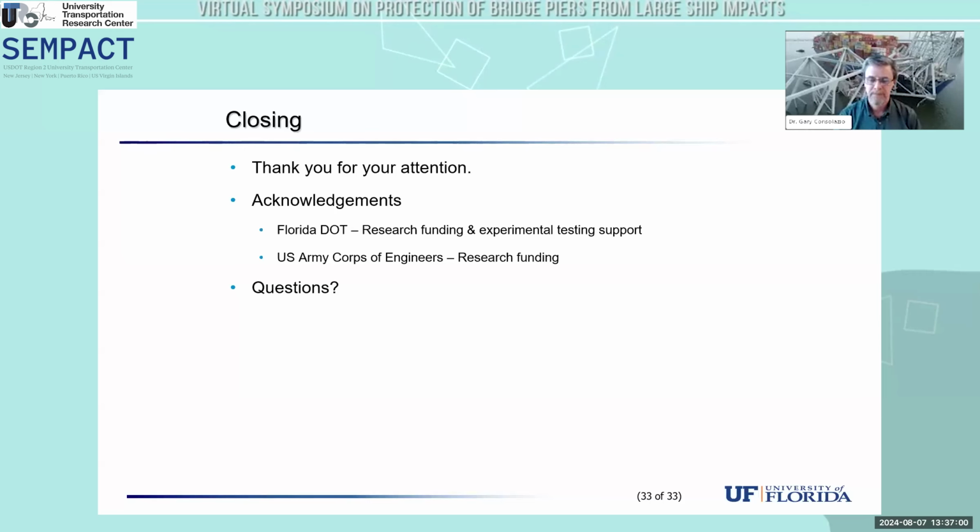There was a quick question here from John Horvath. Have you tested a pointed or knife-edged pier shape? I didn't see that in your presentation, though. We have tested relatively sharp angled shapes, and with vessels such as barges, they tend to split.